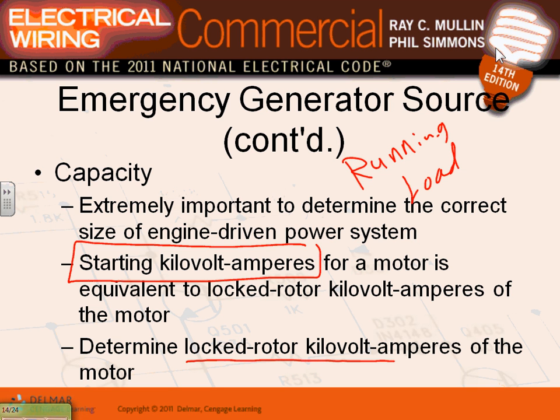So when you size a generator, for emergency, legally required, or any of these systems, you have to keep two things in mind. How much KVA do I need to run? That's this amount. And then how much KVA do I need to start at one step? That's this much. Based on these two criteria, you can get a certain size generator.